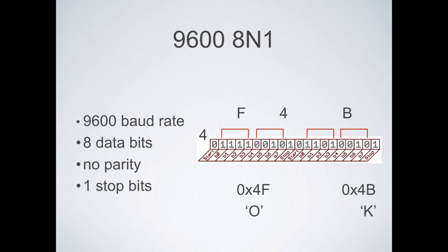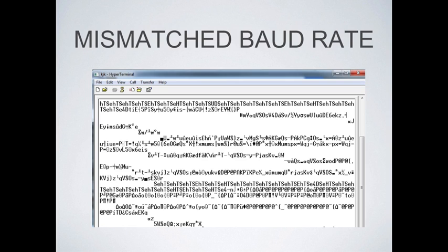So when you're hooked up to the serial interface, there are times when you may select a mismatched baud rate, and this is kind of what it would look like. A lot of gibberish just coming across. That means you're off your clock, or your clock is not syncing up with the other person's clock. And what you've got to do is find a way to receive data at the same clock rate, such that you can get the correct data.